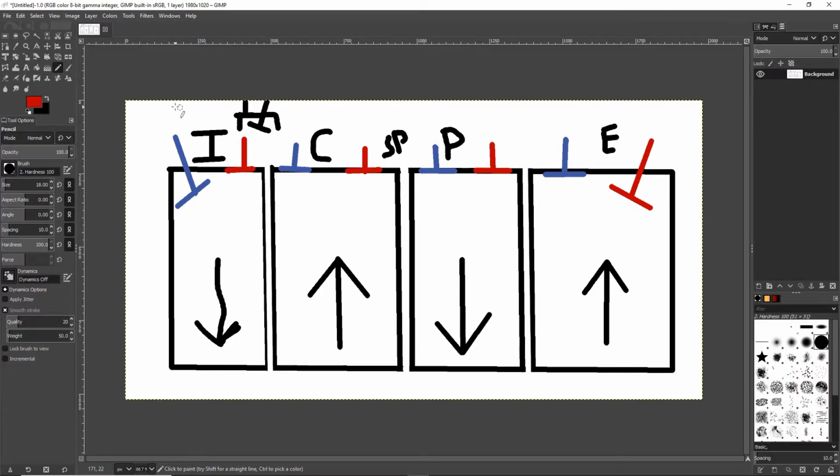Now, we just went over a lot, and I'm going to help you the way it helped me. Intake, compression, power, exhaust. On the intake stroke, the piston moves down. If you can remember that, you know which way the piston is going across the other three, right? The intake valve was only open on one stroke, closed on all of them except for the one stroke, and they called it the intake stroke. Oh my goodness, that should be easy to remember. And the same thing for the exhaust. It's only open on one stroke, and they call it the exhaust stroke. Imagine that. So that's how I remember it. Hopefully that will help you guys remember it that way. Commit this to memory. We are going to go over this.